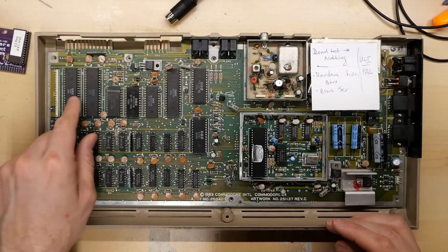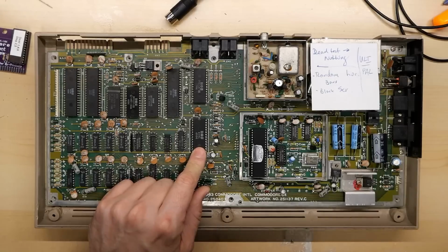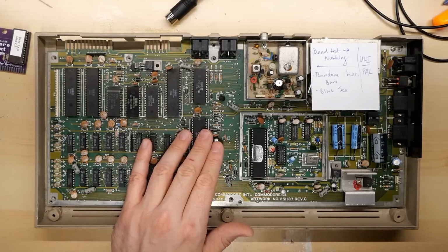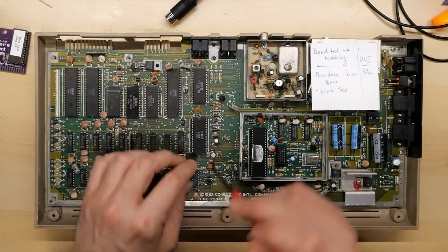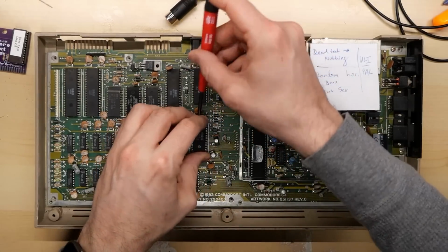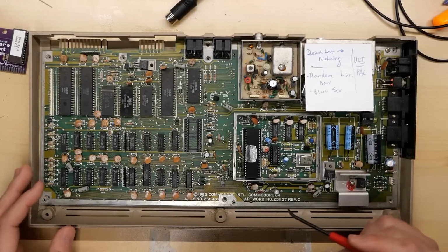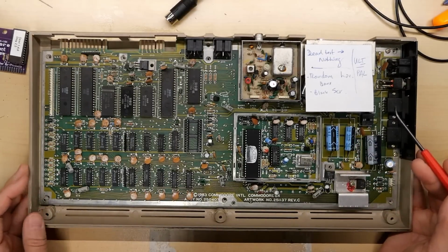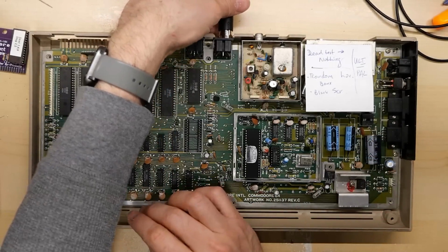So it's got all soldered chips except for the VIC-2 and the SID. So that's cool. The SID's actually in here. I'm just going to remove the SID while I'm here. We don't need to do any testing with this in here, just in case something goes wrong and kills the SID chip. Judging by the note, I already powered this thing up before. I just don't remember how much troubleshooting I actually did when I powered it up. So might as well start from scratch again.